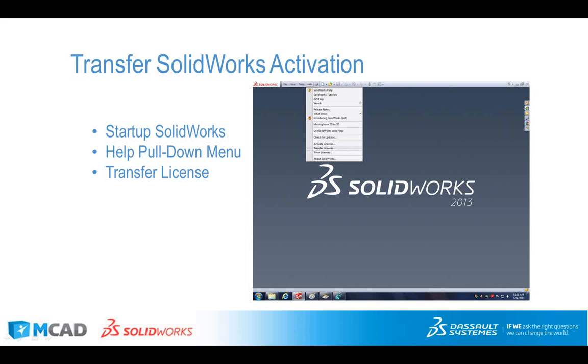It's certainly not required because if it is the exact same computer ID, it will recognize that that machine's already holding onto the activation. Now, if you want to install SolidWorks off another machine that you're done with and you don't transfer the license first, then as far as activations go, that machine is still tying up one of the serial number's activations. So that could be a problem, and it could prevent you from installing on your new machine. If you're not familiar, on that Help pull-down menu, near the bottom you'll see Transfer License.